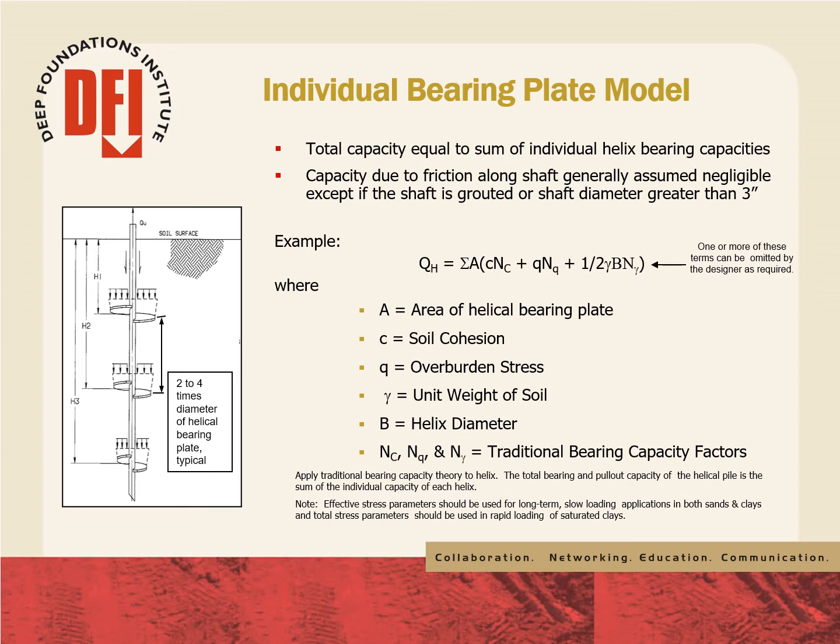Bearing capacity is calculated using the Terzaghi general bearing capacity equation. The designer must make use of the appropriate soil parameter, either effective stress parameters for long-term slow loading in sands and clays, or total stress parameters in rapid loading of saturated clays.